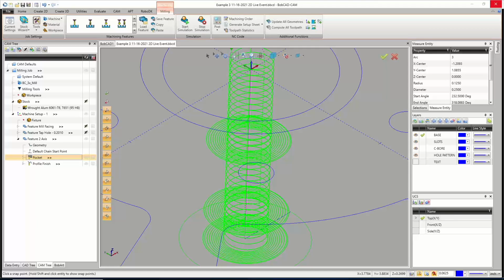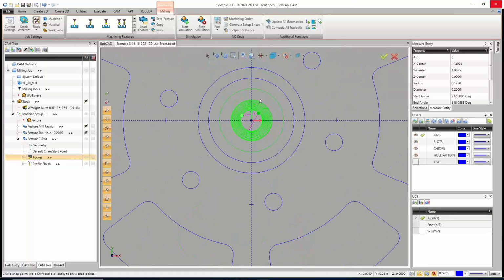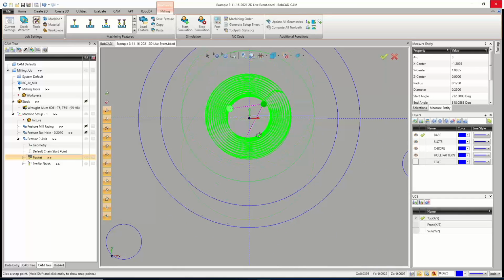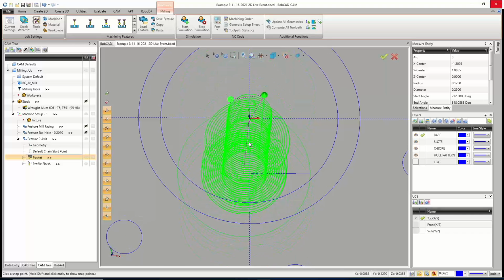Not bad overall. Let's go to a top view. The big thing you want to pay attention to when you're looking at this is your spiral, which for us is right down the middle, which is a beauty. Sometimes it'll offset the spiral depending on the shape of the pocket. Round pockets, it tries to go in the middle.